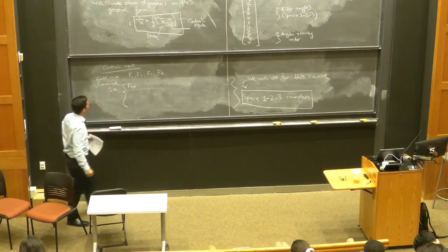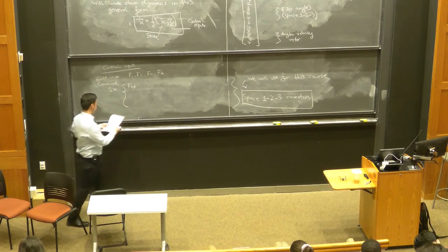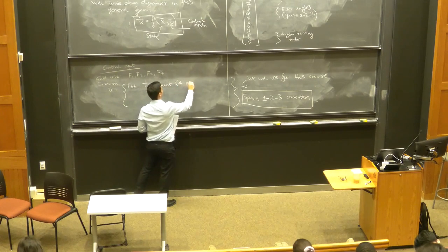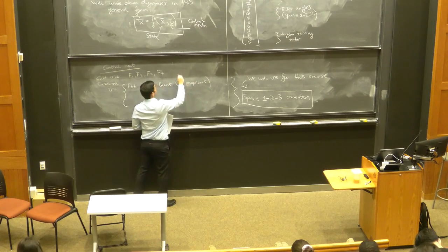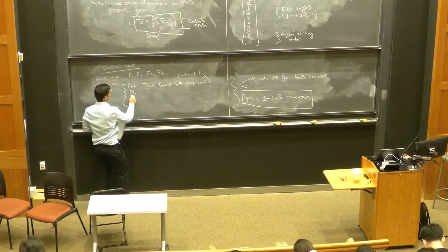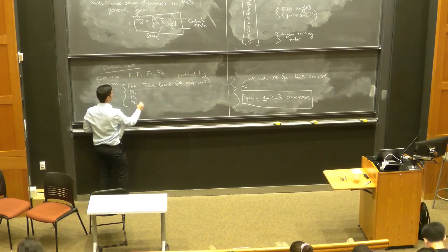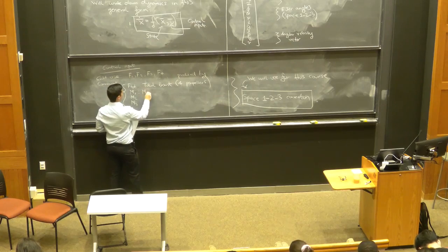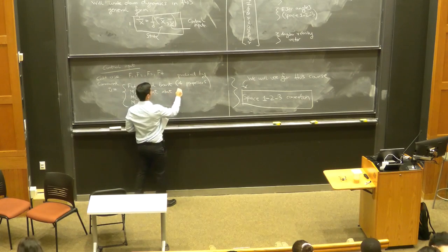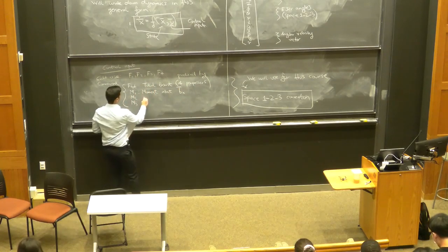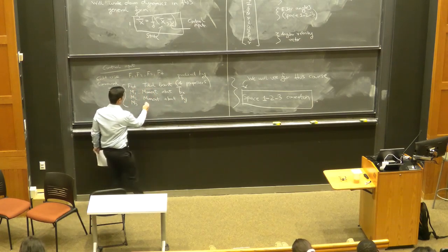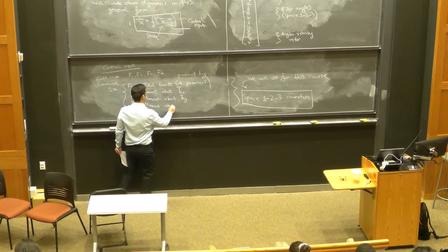The first component of the control input vector, I'm going to call it F total. This is the total thrust, just the magnitude of the total thrust produced by the 4 propellers. And the other three components, I'm going to call them M1, M2, M3. This is going to be the moment, the torque produced by the four propellers about the body x axis, Bx. This will be the moment about By, and the moment about Bz.